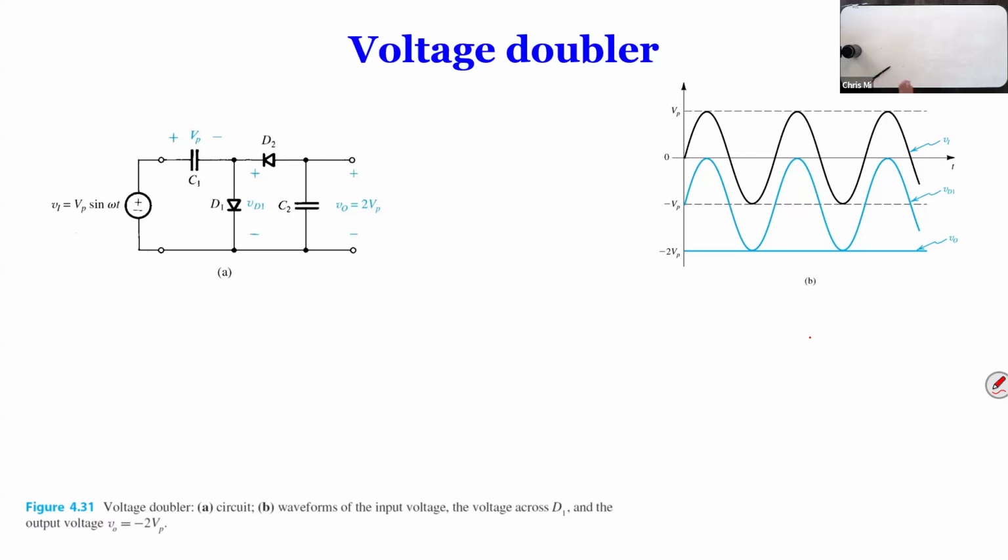If you look at the left hand, C1, D1. Is this going to assemble the circuit we said, the DC restorer? Flip back your slide to see that circuit. Is that the same? No, the diode is flipped, right?